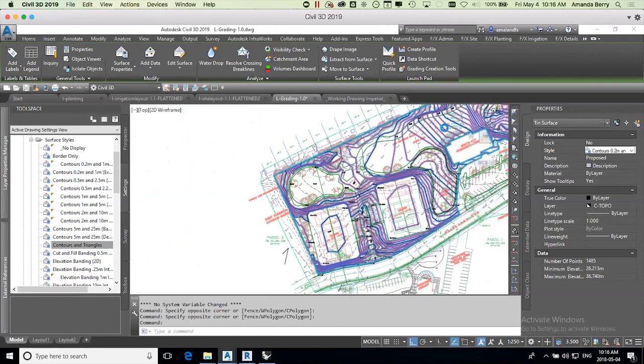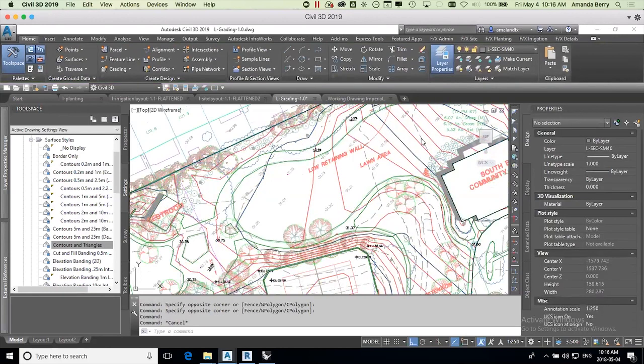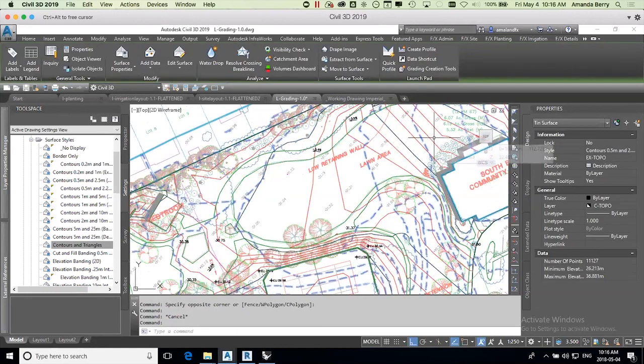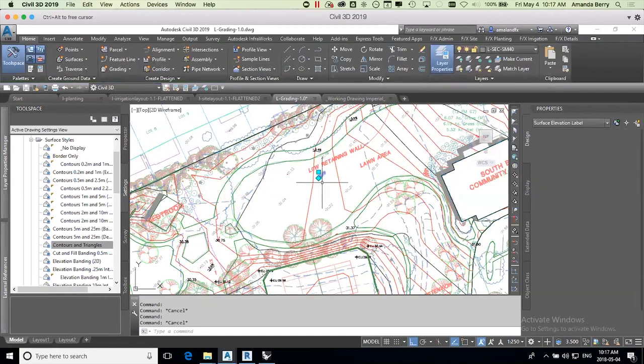And I actually have this as a surface as well. I got a survey into this drawing, so I'm already connecting with surveyors because they almost always are able to give you a DWG with these spot elevations here, or I have gotten an XLS format survey before, and I have been able to import it. It takes a little bit of massaging to make it into a 2D drawing, but you absolutely have that connection and can import that into CAD and create these little points right here that are basically feeding all of these features.